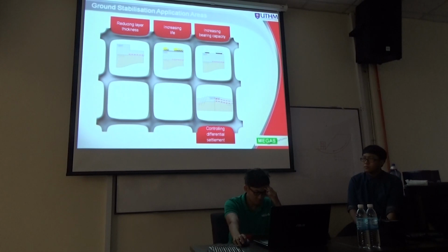You can try to observe maybe after 3 months, after 6 months. It will happen in the transition between the old pavement and the new pavement. There's a differential settlement. Maybe next time you put some attention onto it. When you see they do the widening, keep in mind 3 months later, 6 months later, have a look. It always will happen. The reason is, once they open this up, it's subject to the traffic load, then the consolidation rate at the widening portion becomes faster. So always at the transition of the new pavement and the old pavement, we have the differential settlement.